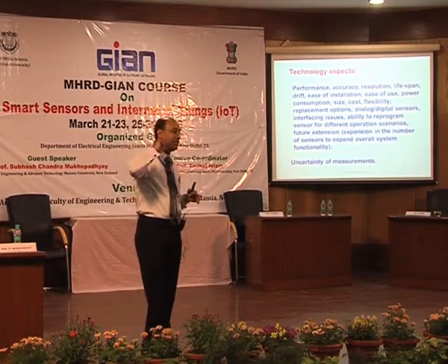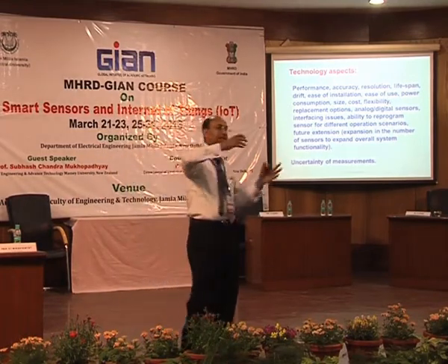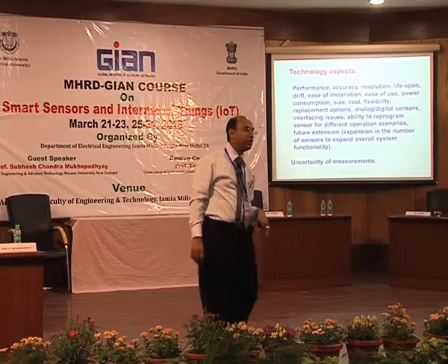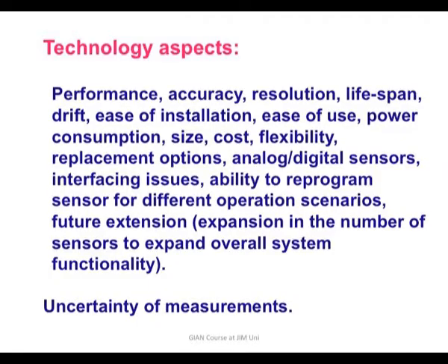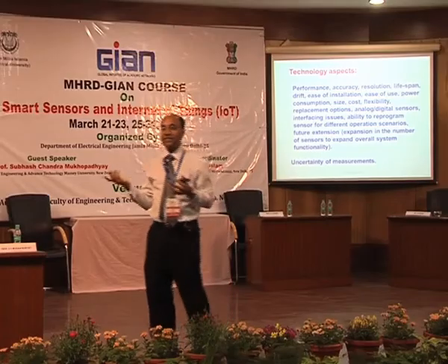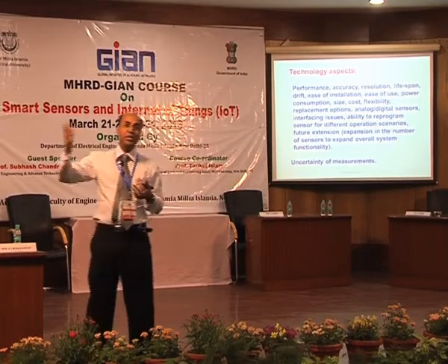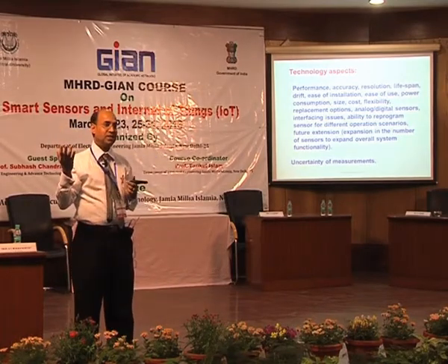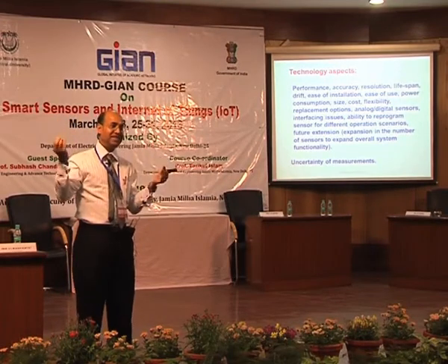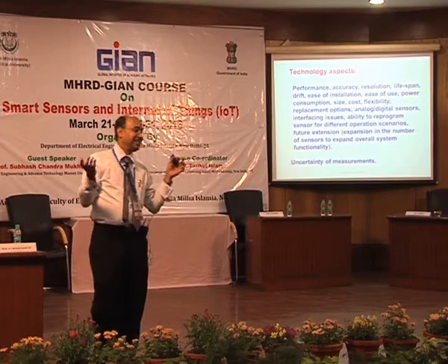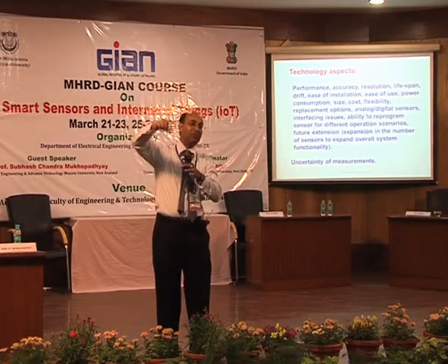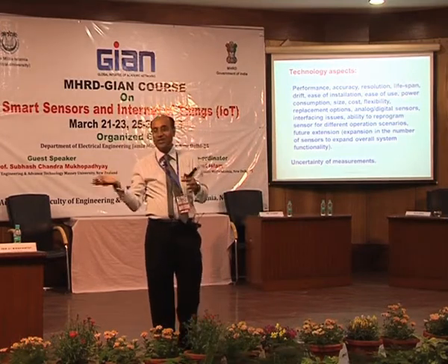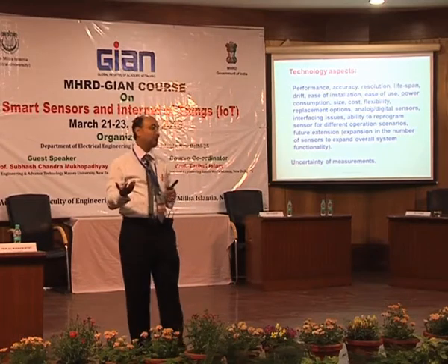Sometimes if you go for one sensor, you get the data for this room, maybe 21 or 22. But if the sensor gives you 25 or maybe 35, you may have a feeling that the sensor is wrong. But when you have the system, you cannot do that, isn't it? So sometimes you may say I don't rely on one sensor, I go for 2, but now the 2 behave erratically. What do you do? You take the average. So sometimes you have to go for redundancy. I go for 3 sensors and take 2 of them which are close to each other. And if you do that, you are actually adding to the cost of the system.